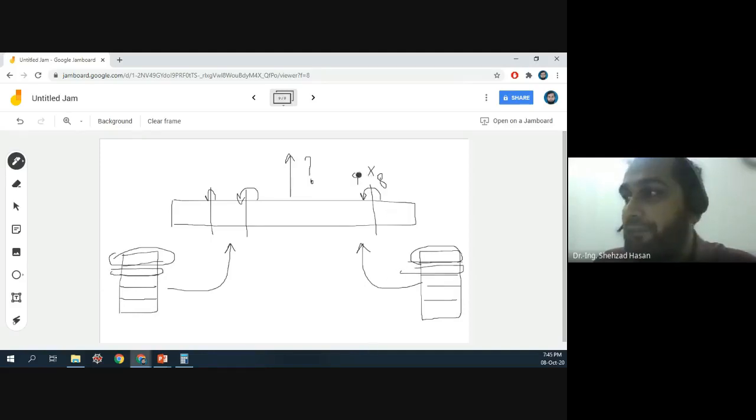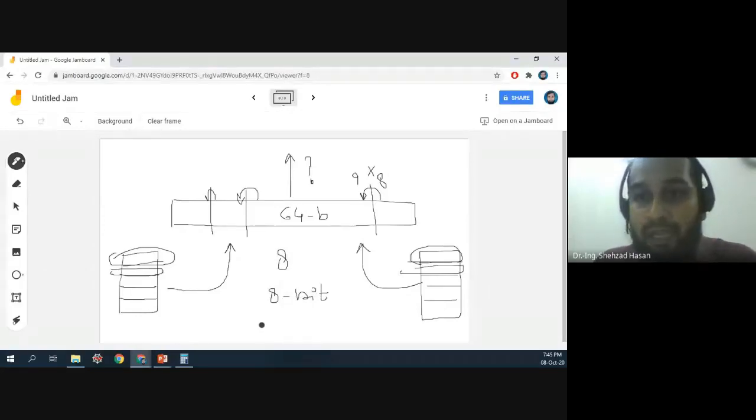Why? Because I have removed these ripple carry effects. So every 8 bits is going to be a separate number, treated separately. So what I have done is converted this 64-bit bigger adder, which can take a 64-bit number, into 8 adders, which can take 8-bit numbers.